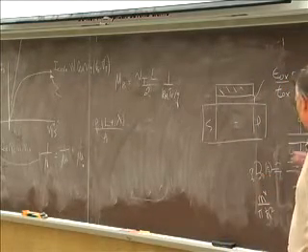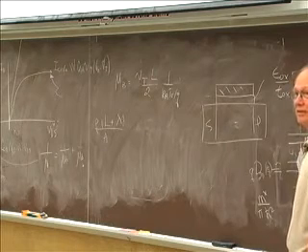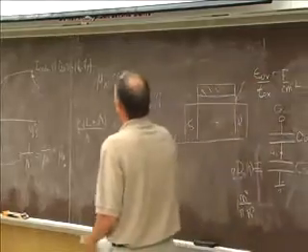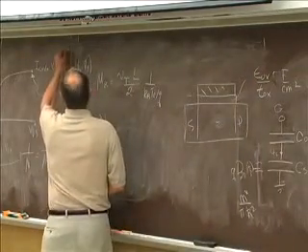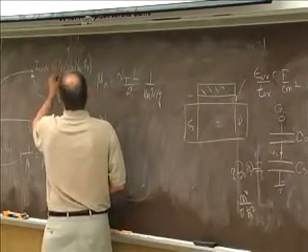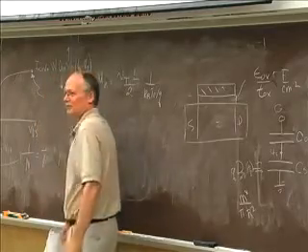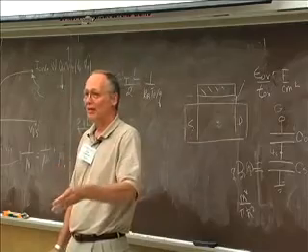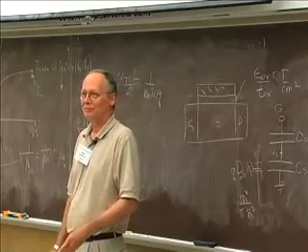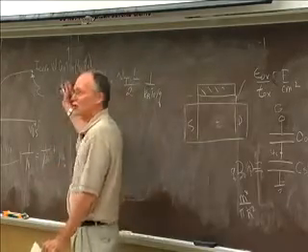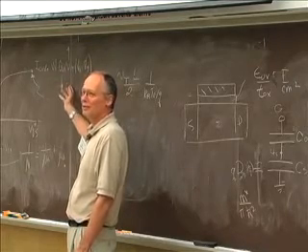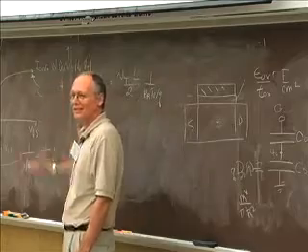If I put these two capacitors in series, it's going to lower the overall gate capacitance. So there's a trade-off. The boost that you get from the light effective mass is offset to some degree by the drop in the gate capacitance. Your charge is going faster, but you have less charge. The net effect is that you get a benefit, but you don't get quite as much benefit as you might have initially anticipated.